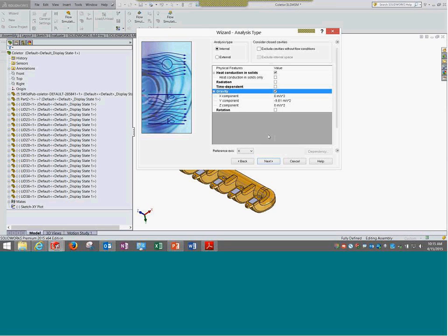Remember, in both simulations the gravity effects will be visible only if the density changes. So typically if there is a liquid which is being heated and the density changes, the lighter part of the liquid can go up and the heavier part can go down. So this phenomenon can be understood, visualized and simulated using the gravity option. Here you can see the directions, etc.